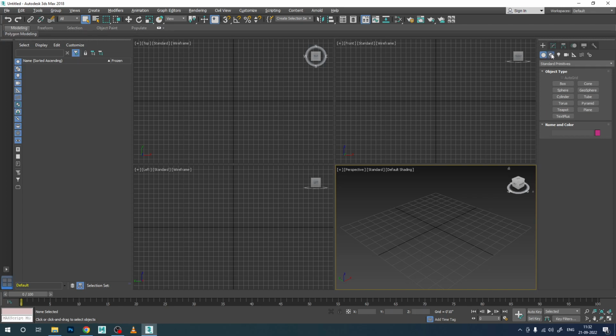So first option, once you come to the create option, geometrical shape you will see. Under this one you are having the second option, that is spline shapes. Take the line tool. Line tool has corner and smooth. If you want initial smoothness, you can have initial smoothness. Corner you have, if you want, you can corner, smooth and bezier. Bezier will give you modification from both ends.